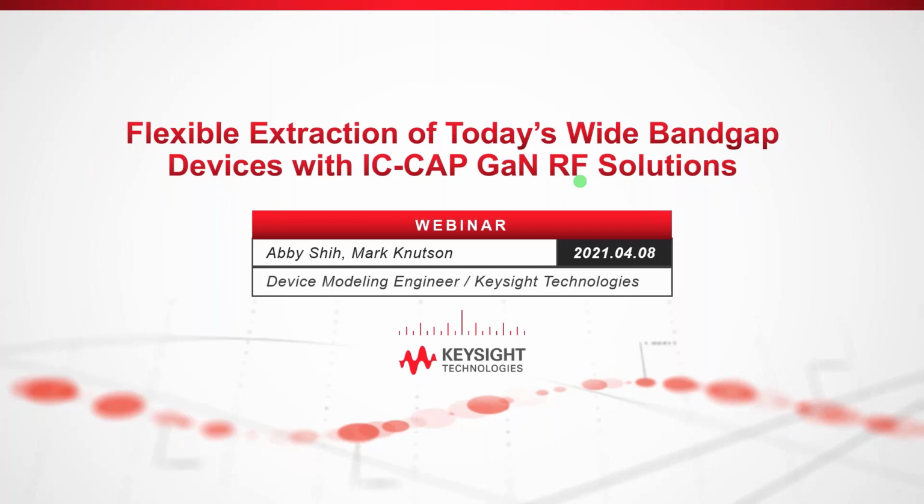We're going to go into the device physics, or I should say Abby's going to go more in depth there, but I wanted to give you a heads up on what's so great about wide bandgap devices, especially heterojunction devices built on a GaN substrate. One teaser is that it can take a larger electric field and a larger voltage, and then at a given operating power you can have a lower current, which means smaller devices. Because of the proportionality of area, that means a smaller amount of capacitance, and then you can get higher frequencies. But you have to navigate some of the challenges we're going to look at today, like trapping, electrothermal effects, and some of the different physics challenges. So thanks for coming today.